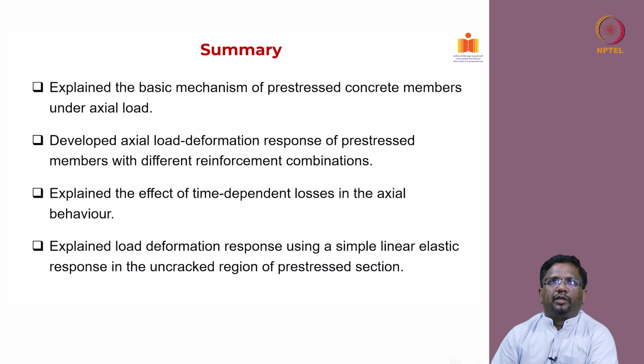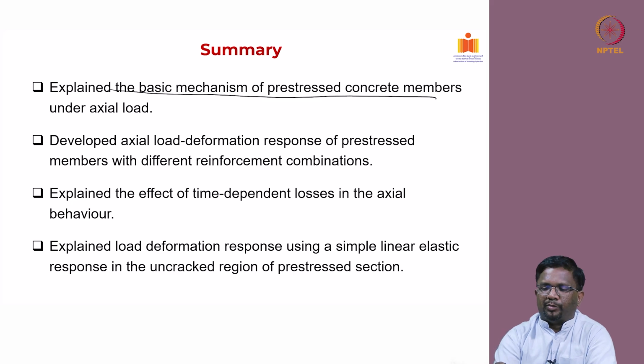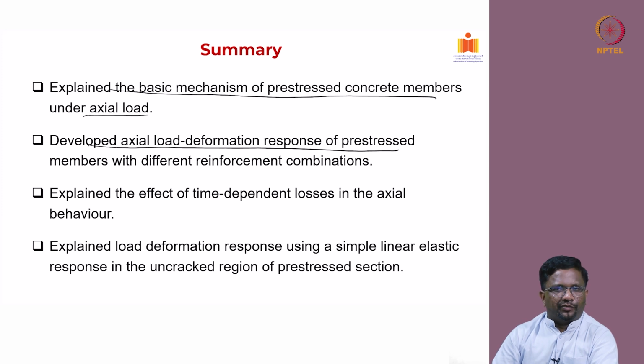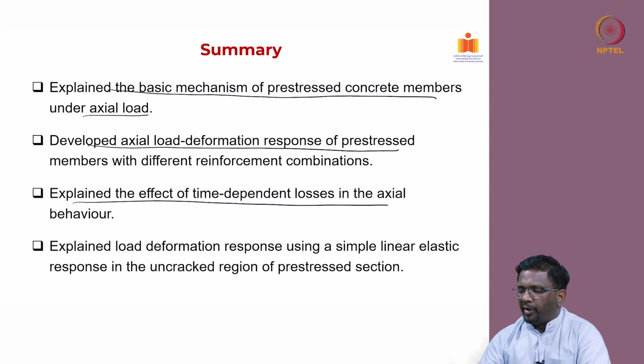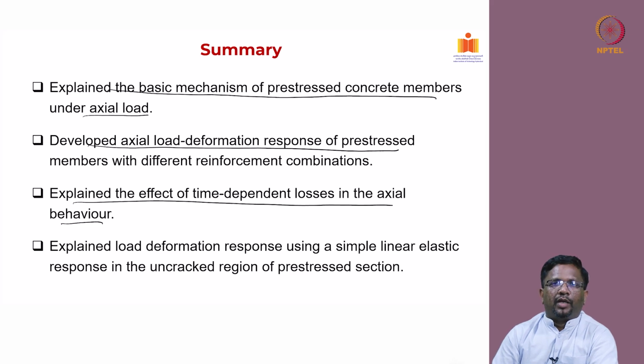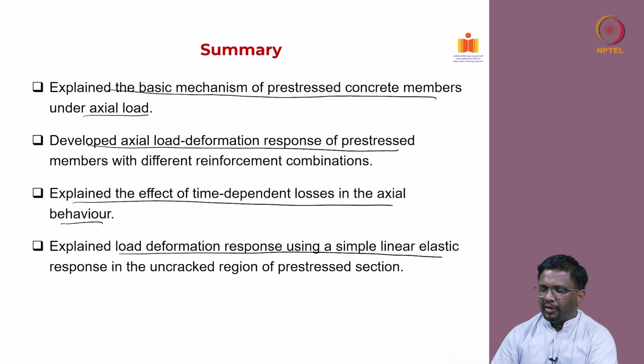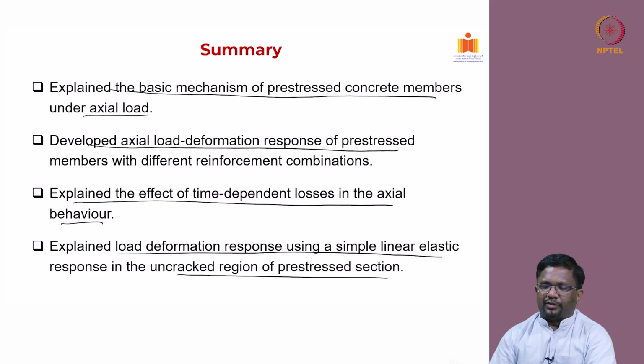So, with that we can summarize what we have discussed. In this lecture, we have explained the basic mechanism of pre-stressed concrete members under axial load, both tension and compression. We have developed the axial load deformation response for pre-stressed members with different reinforcement combinations. We have also explained the effect of time dependent losses on axial behavior. We also explained the load deformation response using simple linear elastic response in the uncracked regime of the pre-stressed section.